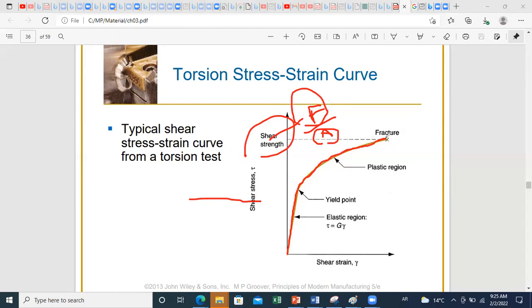The highest force applied will be here at fracture, but what differs the elastic from the plastic region is the slope of variation of this force with strain. Because it's easier to deform, I don't have to increase the force a lot to cause a certain deformation. As I go to the plastic region, I need to increase my force, but at a smaller rate. If I consider a certain delta strain, as I progress, the delta F of increase will be smaller.